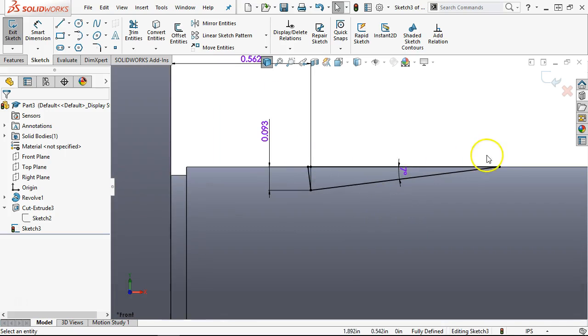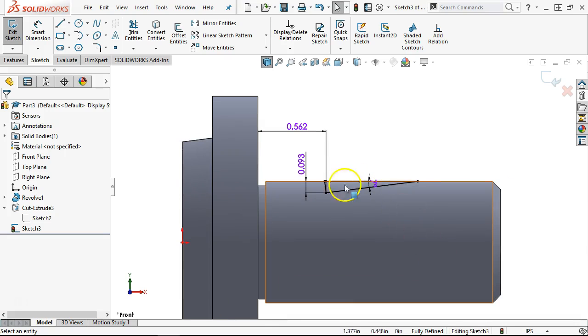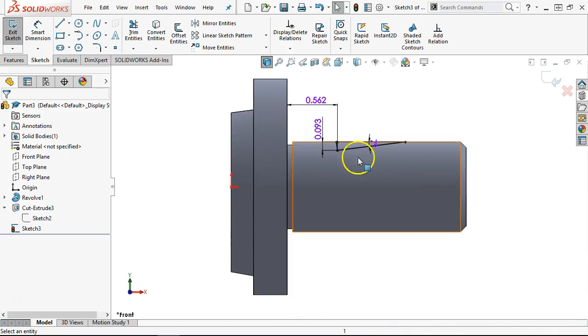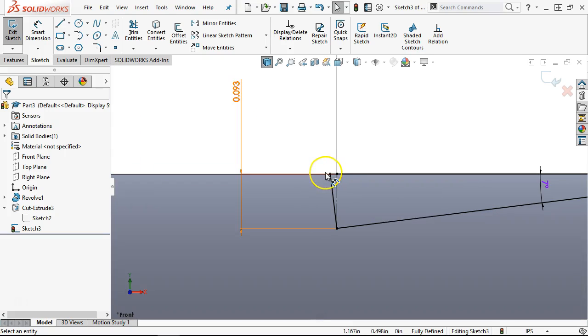If it's construction geometry, then this is the relief. And what I'm looking at is if I set this up at the angle, I can just run an end mill. Let's see where it'll turn. I can run an end mill across that face, and that little bit of extra, if it's not contacting or providing something as a location, I'm not real worried about it. It just improves the manufacturability.